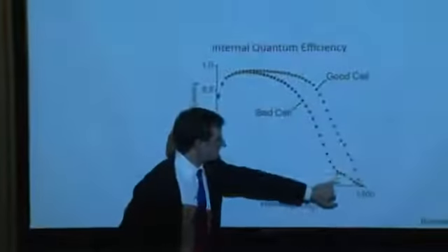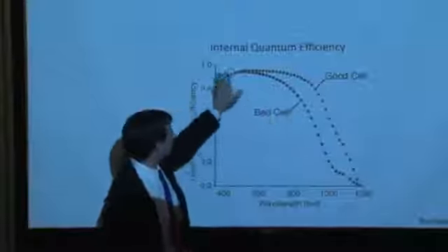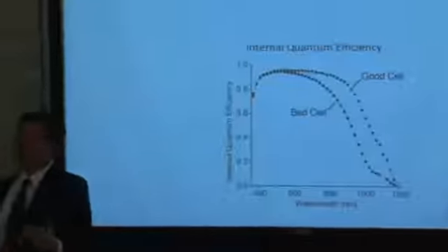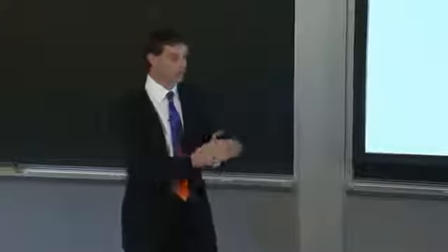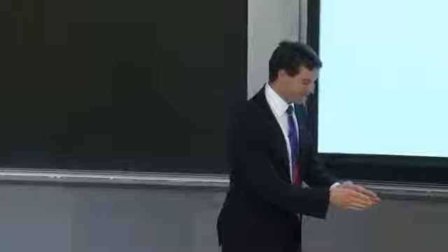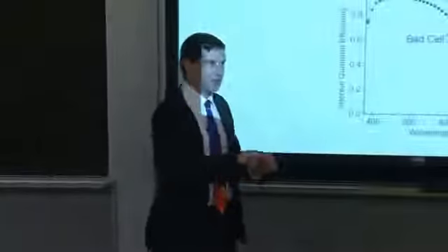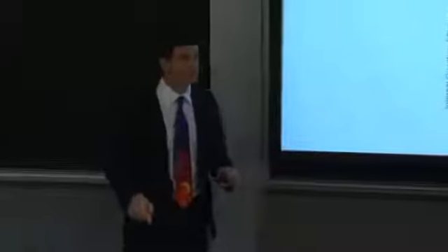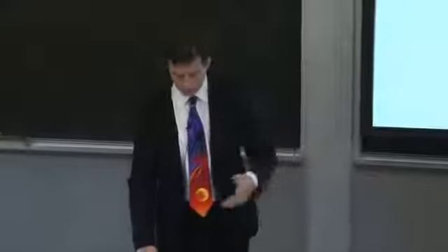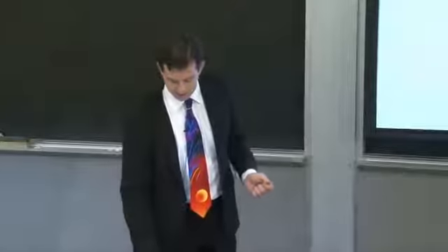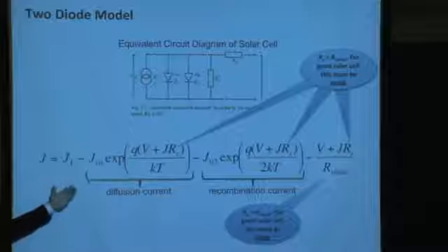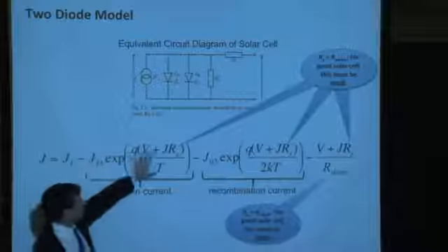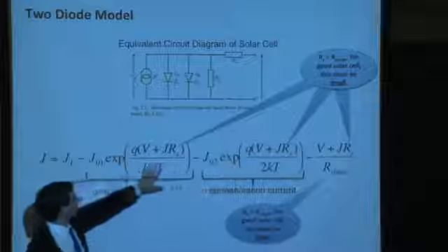You're measuring the spectral response at each particular wavelength, what the collection probability is. Then if you multiply by the total number of photons in that wavelength range, you're determining the total number of carriers generated within that frequency range of light. And then if you add up all of the little bins, you get all of the carriers generated by all of the light, right? And you can adjust depending what spectral conditions you have, say AM1.5 spectrum. So the J sub L here is our short circuit current, effectively, and what is derived from a spectral response measurement. The rest of these terms here are of interest.